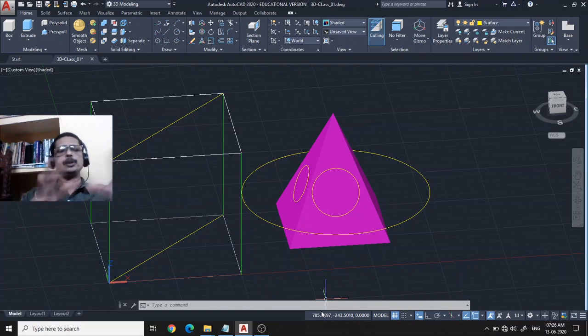So if you want to make a 3D drawing which will have too many components and other things, then basically you'll have to think about creating different UCSs and saving them by giving some names and calling them later, and again drawing something on those planes. So this is the basic concept about UCS. This being one of the important aspects as far as 3D drawing is concerned, that's why I'm spending much time on discussing this UCS.